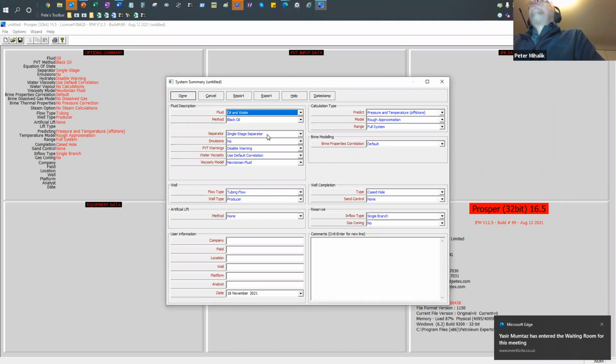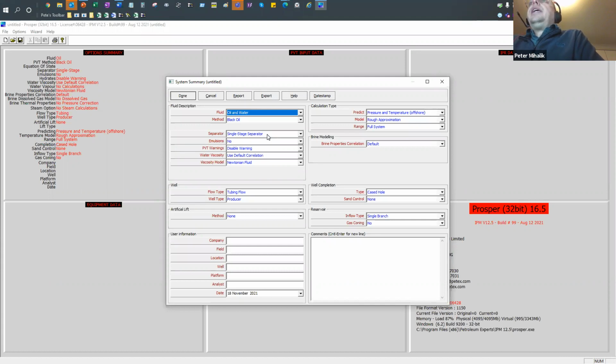Essentially what you do is when you create a black oil PVT model, which you tend to export from an equation of state model, you take into account the separation pathway of the field itself, because the separation pathway that you choose to use ends up giving you a fluid at stock tank conditions which has either less or more gas still entrained in it.